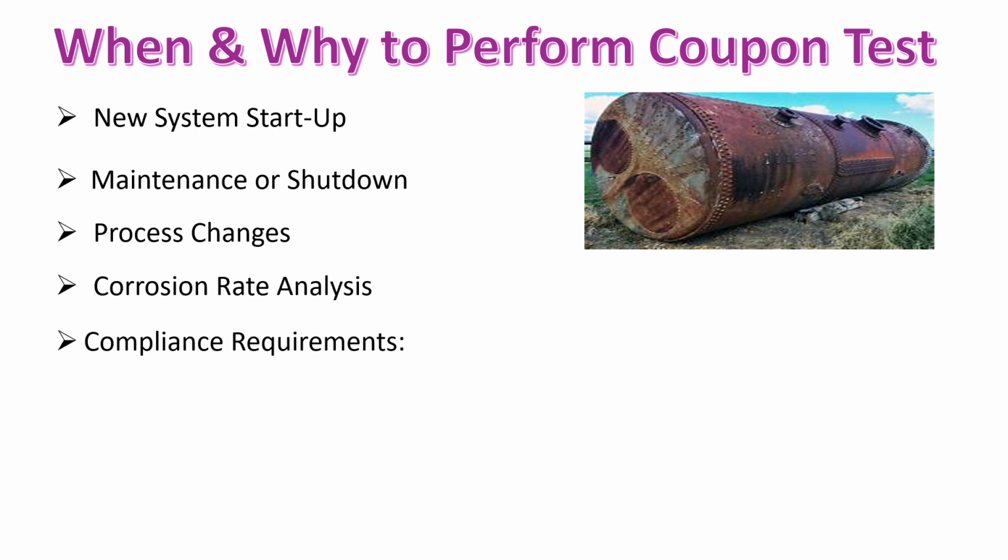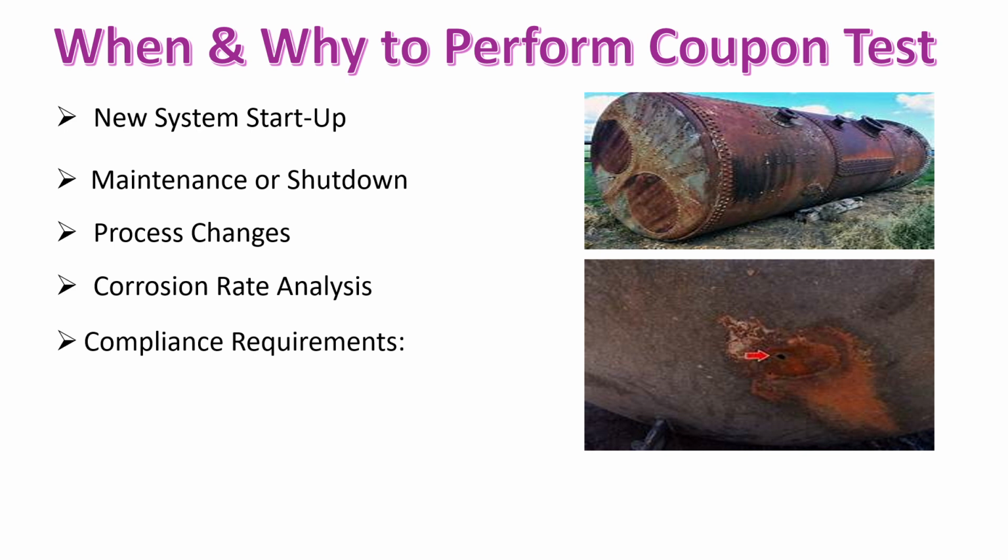And these are some images that give us an idea about what will happen, or how material compatibility is a major concern while selecting the appropriate material. Otherwise, the vessel gets corroded, or sometimes the vessel may get pinholes or leakages during operation.